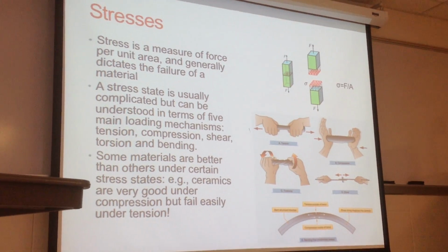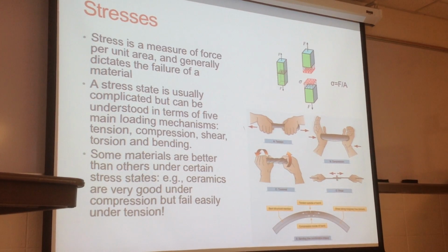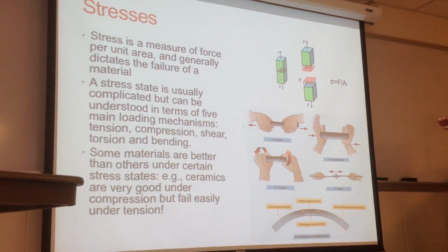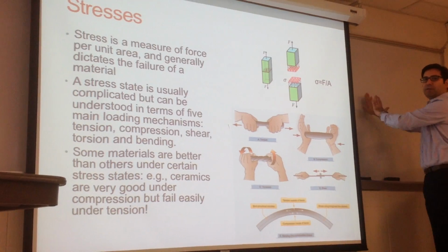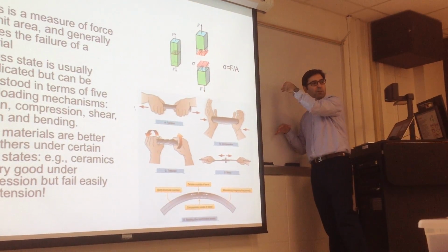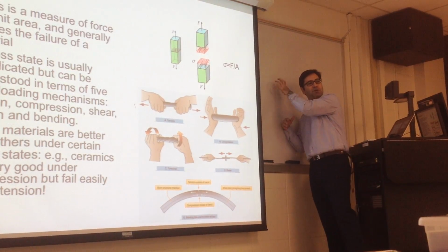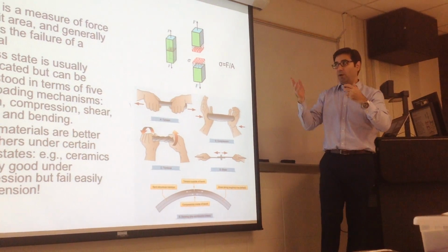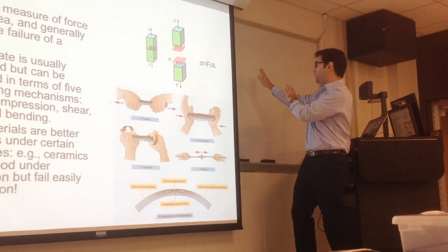So stress is force per unit area. It's more complicated than pressure because pressure is generally just normal to the surface. So if I put my hand here and push in that direction, the force that is generating that pressure is always normal to the surface, whereas for stresses, the force could be tangential too.